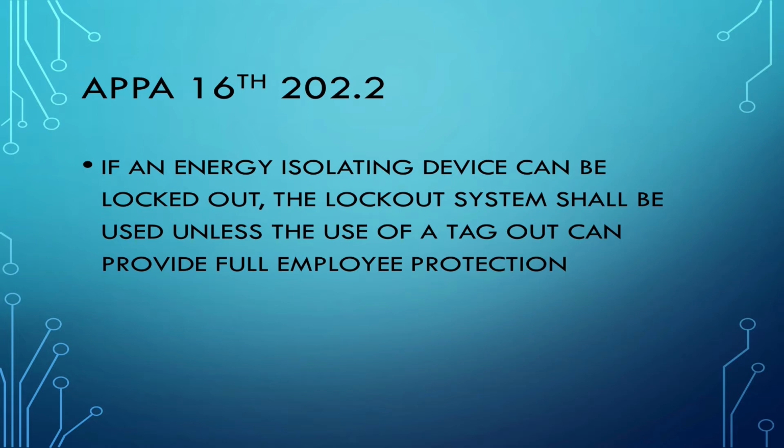The introduction of SCADA, which is not new anymore for most of us, changed the tag because of dispatchers operating breakers and switches, hotline tags, de-energizing, even re-energizing after an outage is handled. Some companies have different procedures and policies as far as who is responsible for filling out the tag, where it's located, who actually has access to it, so be sure we're all clear within your company on your procedure as far as lockout tagout.